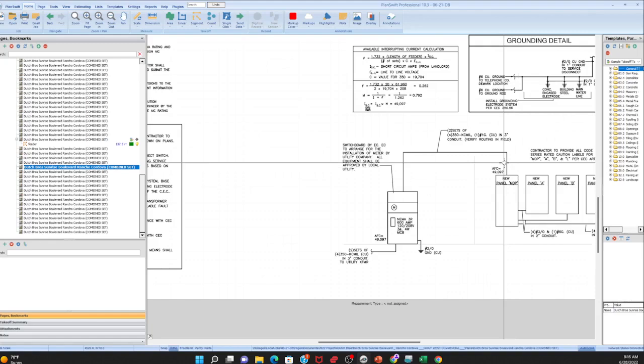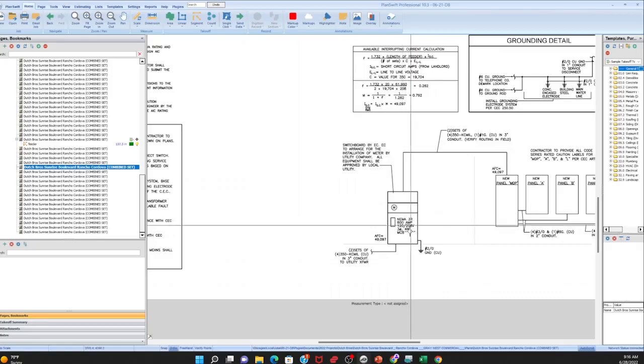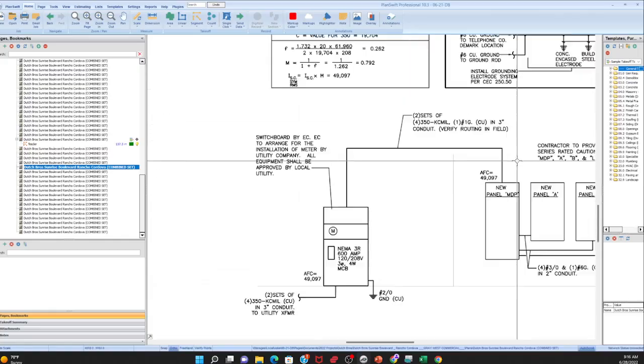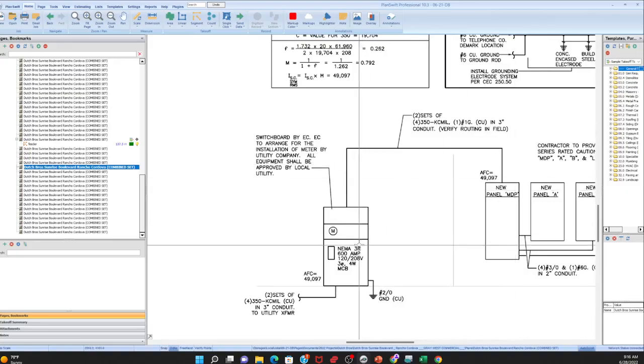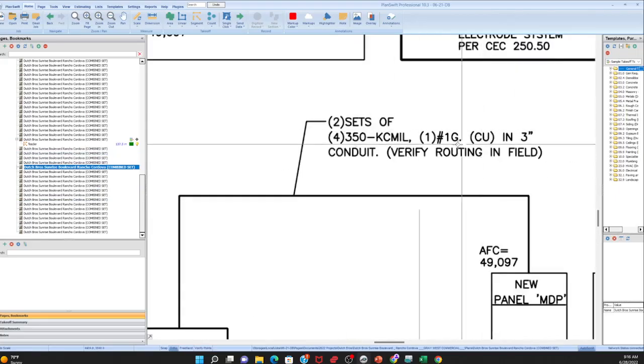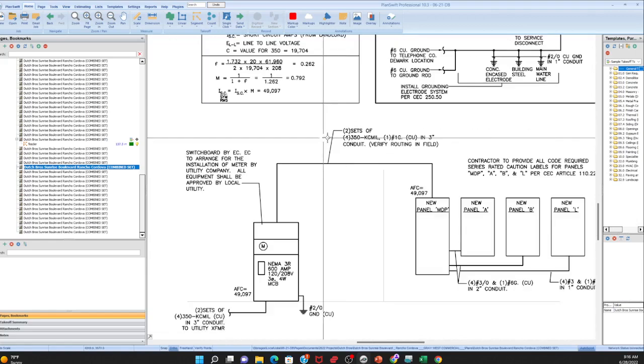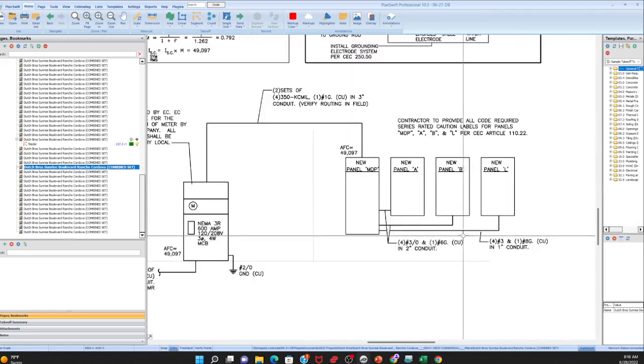Yeah, right. This is PVC. All underground is PVC, all the way to whatever bus duct or whatever they're going to use to connect that to this. And then here is telling you what it is. So now, yeah, you're going to go back to our power plan. And I think we did that distance, right? Oh no, that's a different plan. So we go back to the power plan to measure that physical distance. And then two sets of whatever this tells us. And then, you know, the power plan for all of these distances.